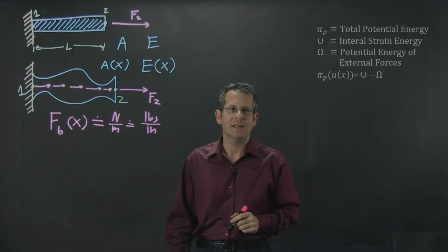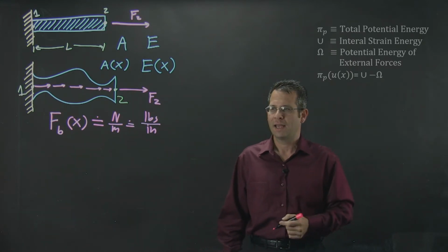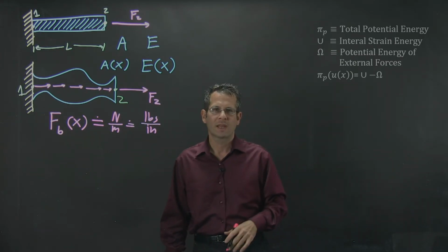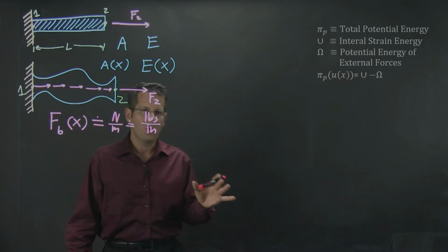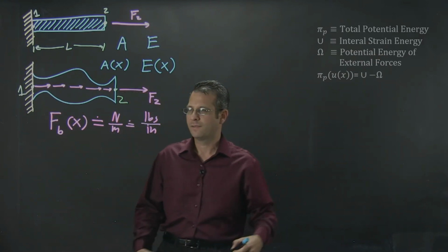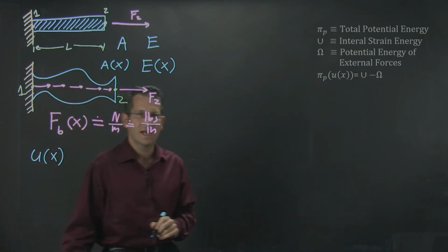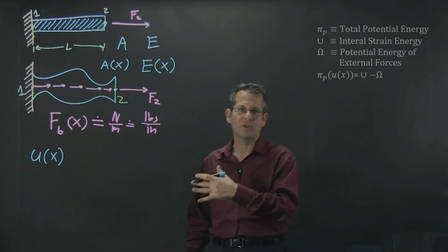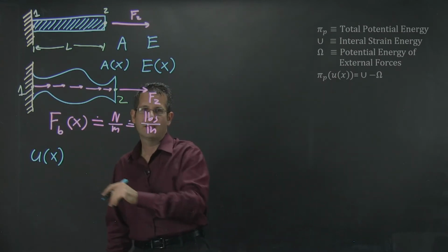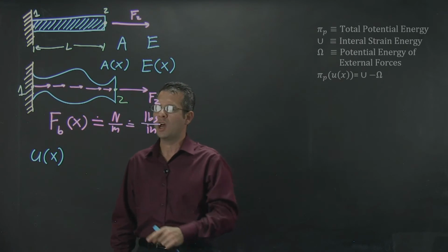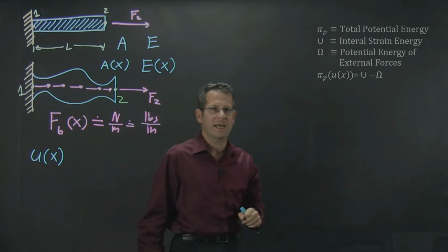We're also going to need those shape functions that we discussed way back in lecture 2, part 4. And why am I going to need those shape functions? The goal of this method is to find the function u of x. And of course, I don't know u of x. That's actually what I'm trying to find. But the method is going to require us to approximate this function, assuming that we know the displacements at the nodes, at node 1 and node 2 in this case.